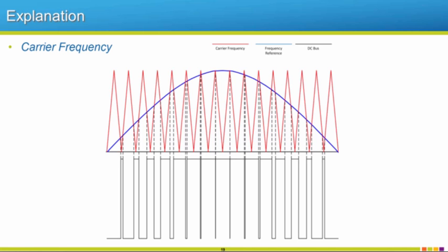Got a question here. What causes noises in the motor line changing gears? Oh, like changing gears. Okay, so what causes noises in the motors? Carrier frequency. You're going to notice if you run a motor across the line, it's going to be real quiet and nice. And then whenever you run it with a drive, it could be at low carrier frequencies. It could be a little more noisier.